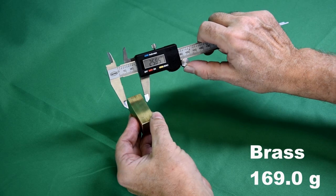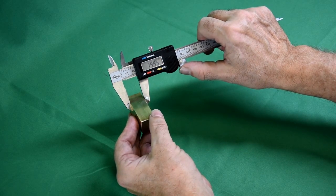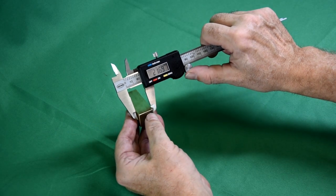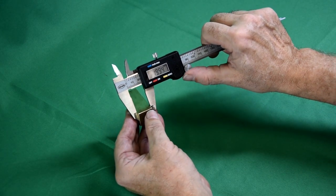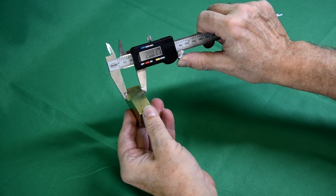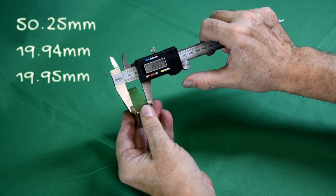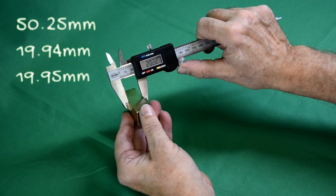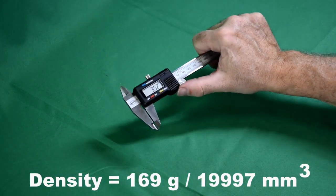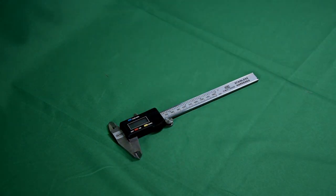Correctly, I am measuring the dimension in 3 separate places to get an average for the width of the brass. This is time consuming, but improves the accuracy again. Finally, here are the figures for the brass block. Multiplying these figures will give you the volume in millimeters cubed. Most of these instruments do need turning off at the end.